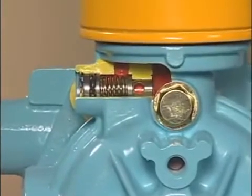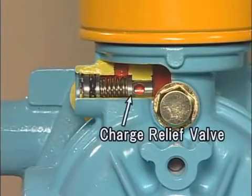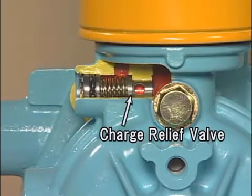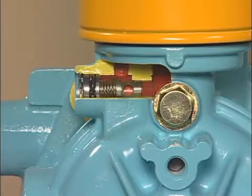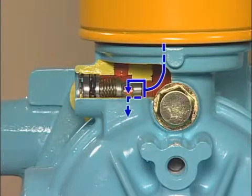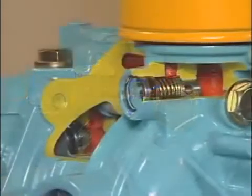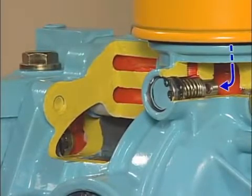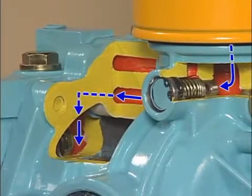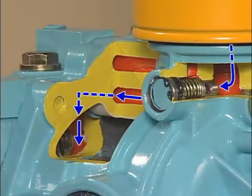This is the charge relief valve. When the hydraulic oil fed by the charge pump is supplied to the oil circuit and HST housing, surplus oil is normally generated. The pressure of the excess hydraulic oil opens the charge relief valve, returning the surplus oil to the HST housing. The hydraulic oil which passes by the charge relief valve enters the oil circuit. The hydraulic oil filling pressure can be set using the charge relief valve.